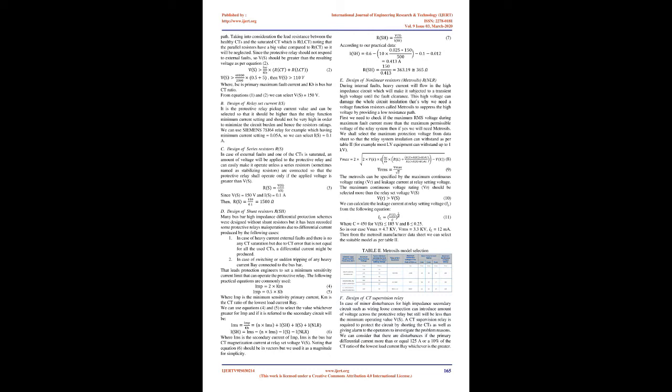A. Design of relay set voltage V_S. It is the voltage across the shunt resistor R_SH at which the protective relay should operate. To design this value, we should take into consideration that this voltage is also applied to all CT secondary circuits in parallel, so V_S should not reach half of the knee point voltage of the current transformers V_K, to avoid CT saturation.